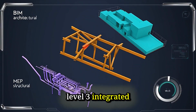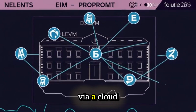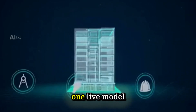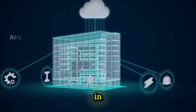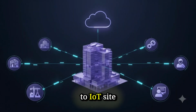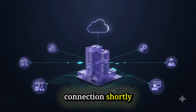Level 3, integrated BIM, a single shared model, accessible to all stakeholders simultaneously via a cloud-based common data environment. No federated models, one live model that all disciplines read and write. Version control, access management, and audit trails built in. This is where BIM connects directly to AI, to IoT site monitoring, and to the GIS spatial intelligence from Part 1. We will come back to that connection shortly.